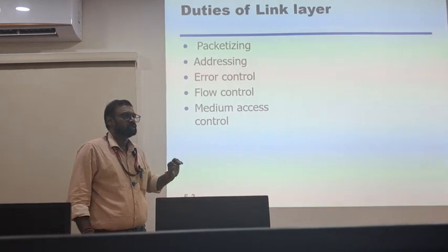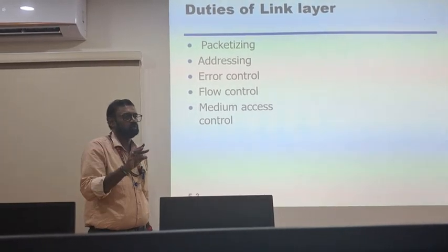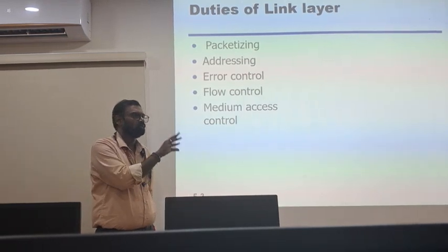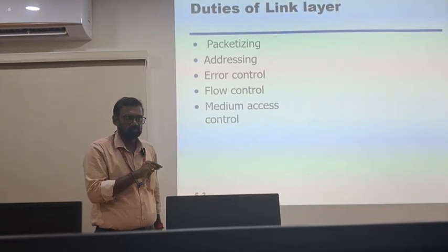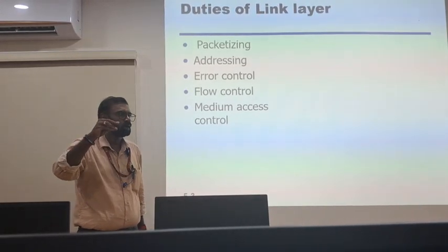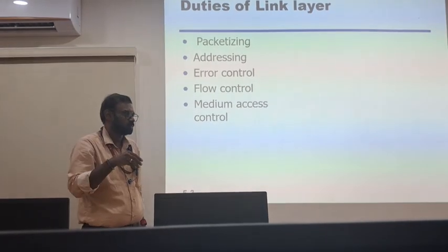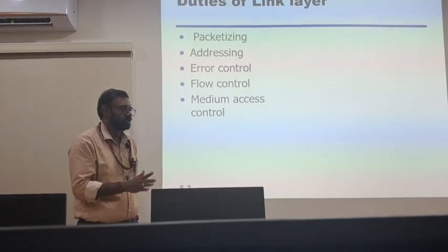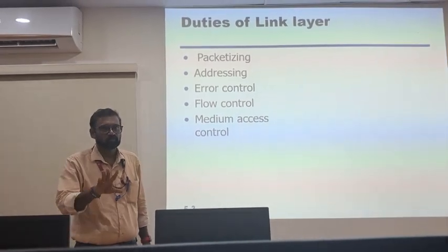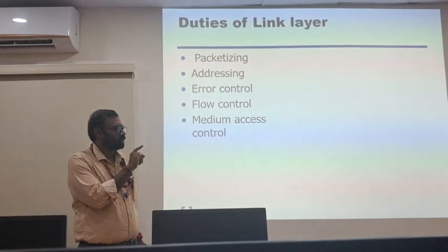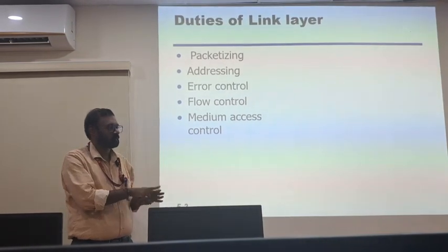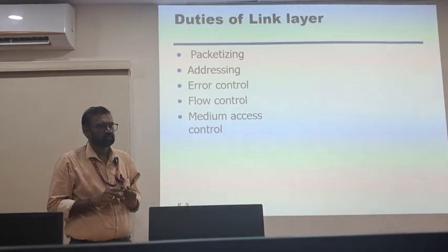So in that case, you are adding some additional checksum value. It is also binary, along with your payload. For example, you are sending 0110. That is your actual data. Along with the actual data, you are adding some 3 bits or 4 bits of checksum value. What is the use? To check for errors during the transmission of data to the other end. Got it?